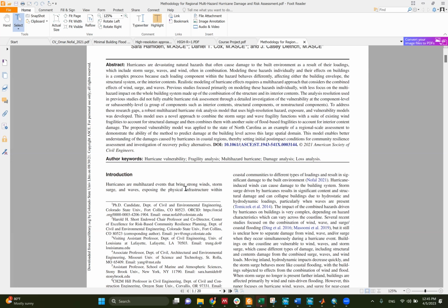We develop hydrodynamic models that capture the spatial distribution of the hazard across the community. And this model, HEC-RAS, is based on finite volumes. Basically, HEC-RAS solves the shallow water equation, called the Saint-Venant equation. If you dig a little bit into what HEC-RAS is doing, it solves an equation like, for example, if you have a slab with a load and you use SAP or ETABS to solve this, we are solving the plate equation using finite element. Same thing with what we do in HEC-RAS. We are solving the shallow water equation to get the water flow using finite volume, same thing. So you'll describe what HEC-RAS is doing, and this is for the hazard.